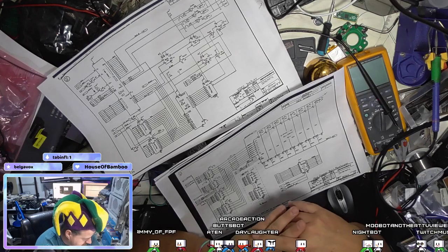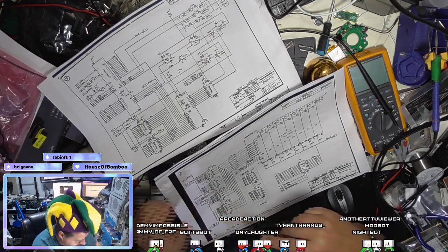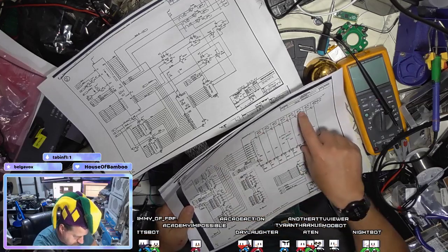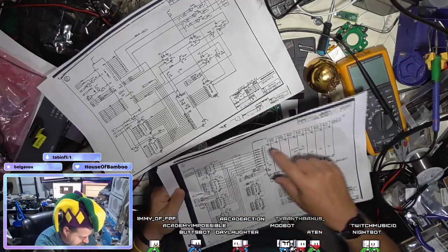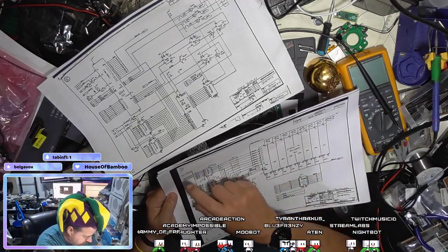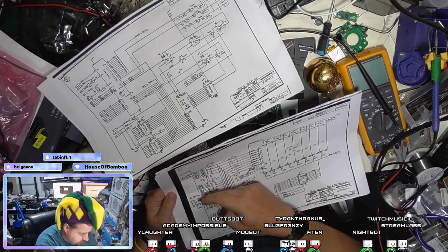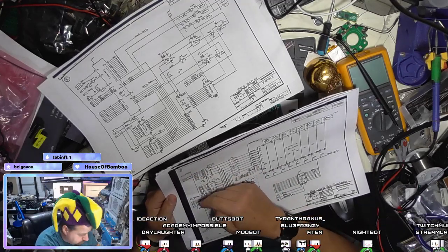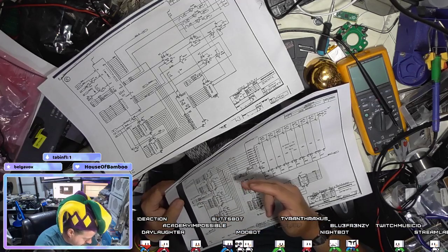So I tested the video RAMs. This circuitry here works fine, but I don't have a way to actually test it going to the video controller chip, because the video controller address pins are not available for me to access.